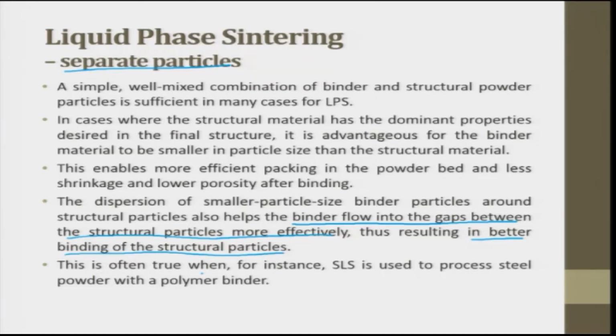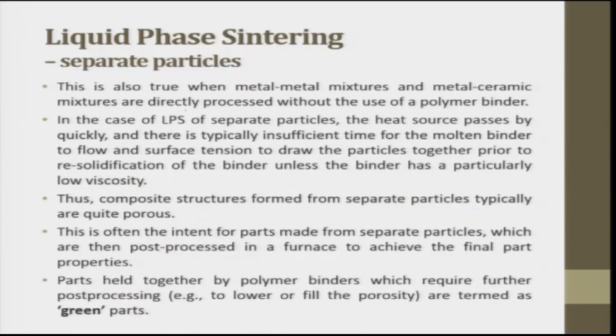This is often true when, for instance, SLS is used to process steel powder with polymer binder. These polymer binders are just left when you heat it, this leaves away, and now the steel particles can join each other and try to form a good compact. This is also true when a metal matrix mixture and a metal ceramic mixture are directly processed without the use of a polymer binder. In this case of LPS of separate particles, the heat source passes by quickly, and there is